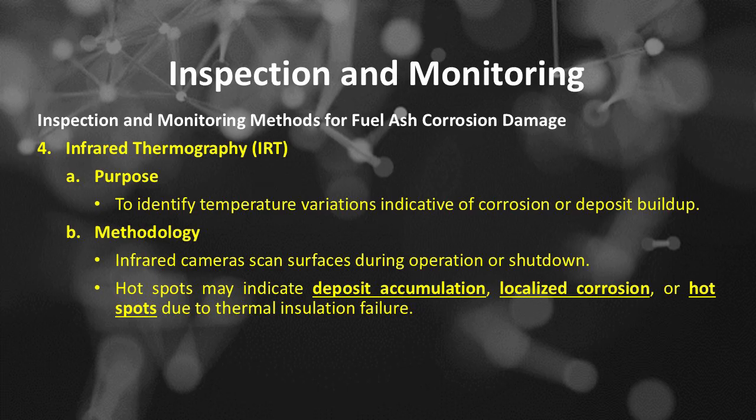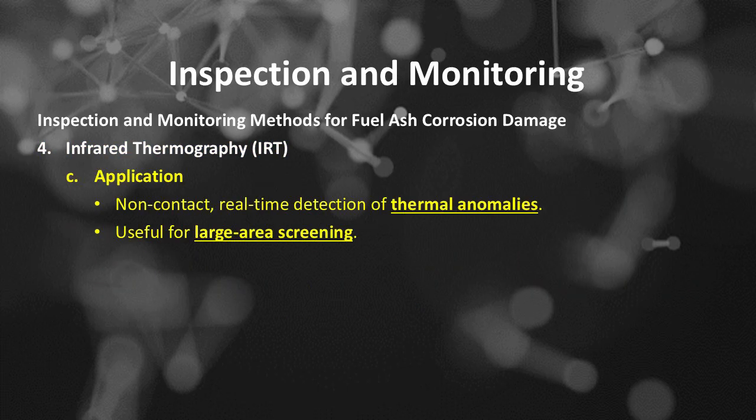Number B. Methodology: infrared cameras scan surfaces during operation or shutdown. Hot spots may indicate deposit accumulation, localized corrosion, or thermal insulation failure. Number C. Application. Non-contact, real-time detection of thermal anomalies. Useful for large area screening.